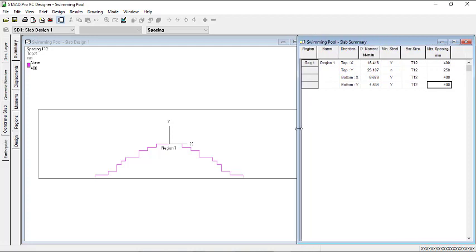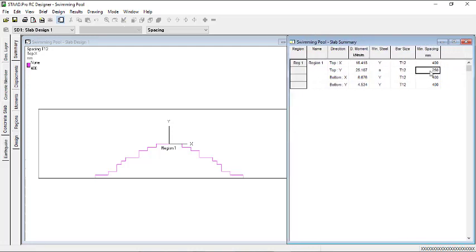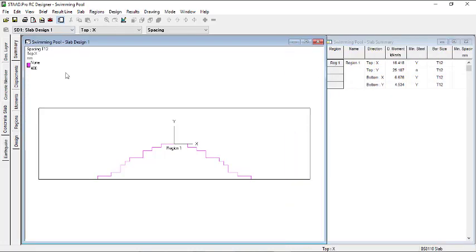So you can see the spacing and everything. I think slab 3 is the bottom. Okay, it is the bottom, is where you have more load. So it will be very difficult for us to use 16 mm for slab 3 because it is 125 mm thick. Okay, so this has to do with design.